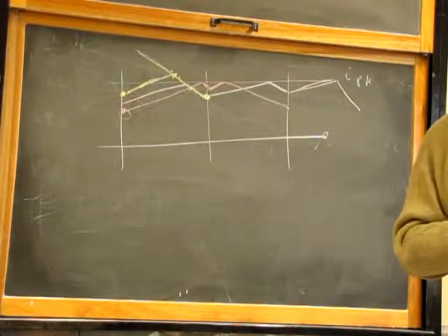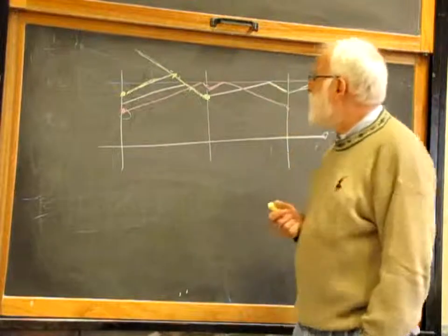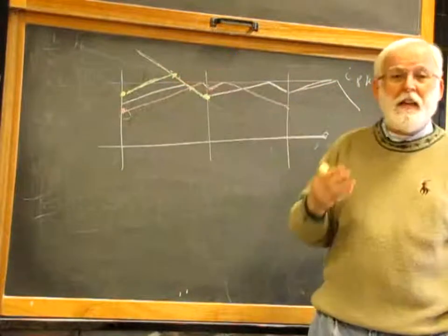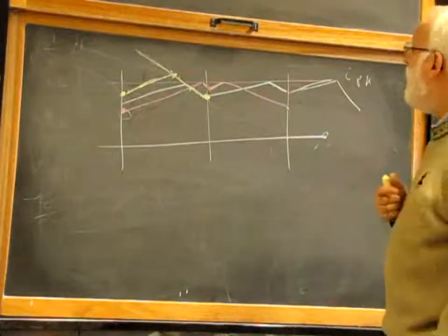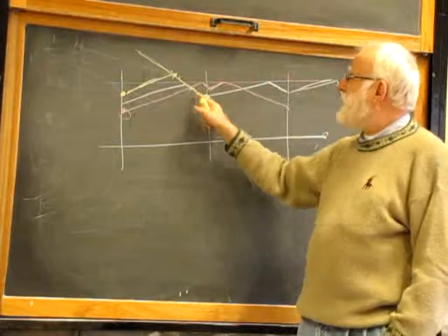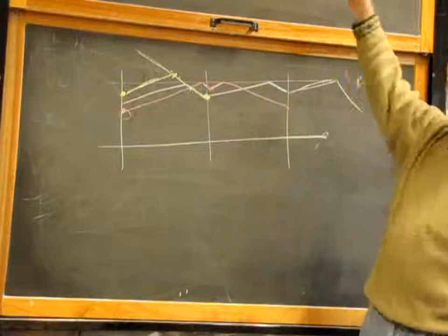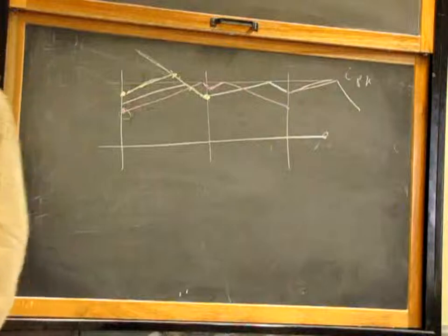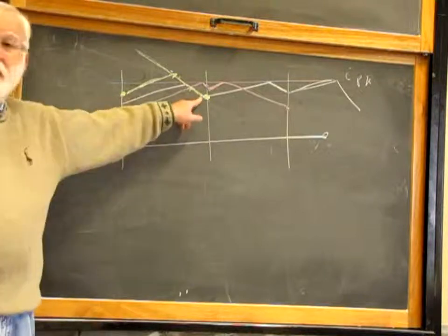In this case, am I not changing the IL level? No. In this case, I'm changing the IL level. Yes, I have to move it a little bit up or down. I have to introduce an offset. But I am not worried about this because the offset is controlled by the integrator that is in front. If I add just this compensation ramp, I change the average level, for sure, because this ramp is not the ramp I introduced over there to compensate for the difference between peak and average. Here, the difference between peak and average is still there. But what happens is that there is no more subharmonic instability.